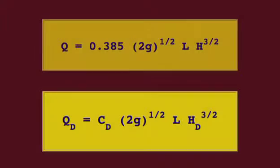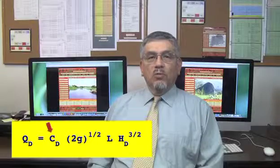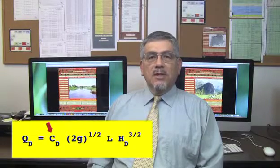The actual design discharge is, in which C sub capital D is the discharge coefficient applicable to the design discharge, varying with relative spillway height in the range 0.385 to 0.492 as shown here.